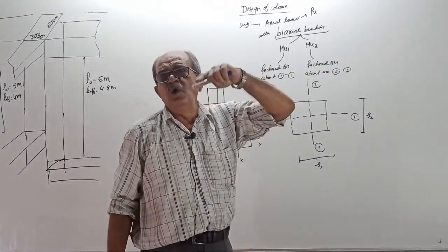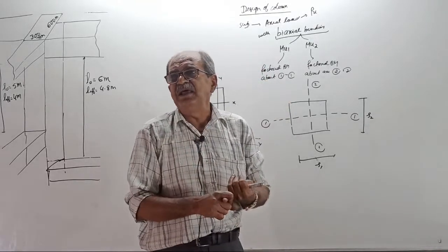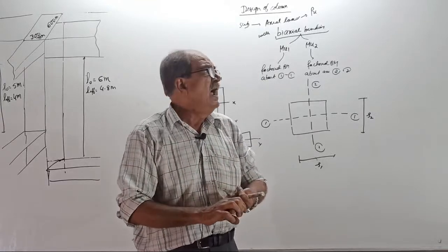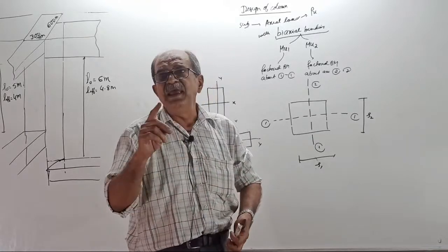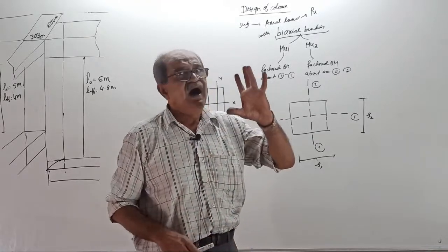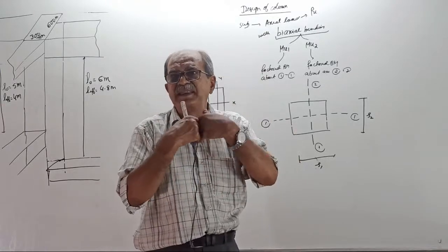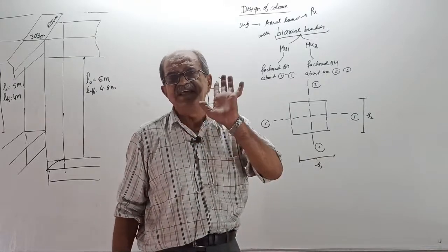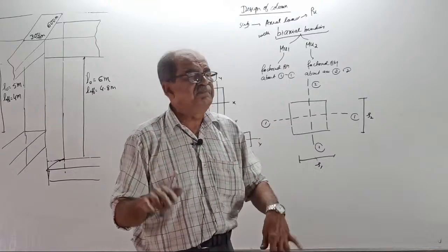In the building, how much load comes, how much BM will come, considering the frame action, the earthquake, the wind load effect, and if it is a long column, then the additional BM, and also the BM due to e minimum. Everything E-tabs will take care of. If you right click, you can see all details there. Otherwise, once you get full confidence in E-tabs, nothing.